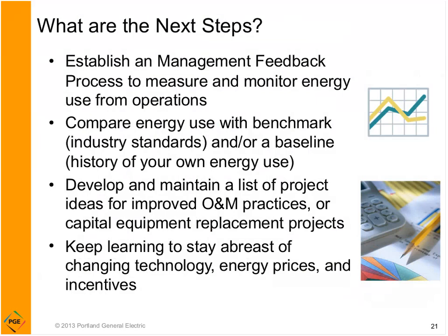So I guess my recommendation for next steps, start measuring. Do the simple stuff of what does my monthly bill look like, compare it with last year, develop that baseline. So establish some kind of system. Do comparisons. You can also get comparisons for a restaurant or a hotel or an office building or a school, what is the average kilowatt hours per square foot? Again, call for help at the Energy Trust or at your local utility or a vendor even. Those standards are available and can provide useful benchmarking.